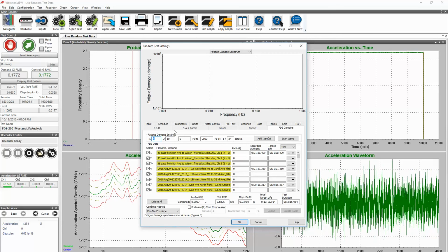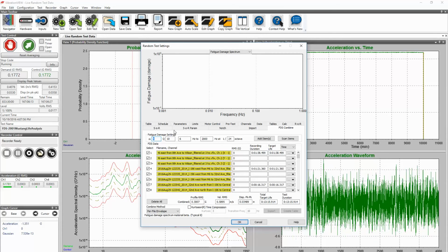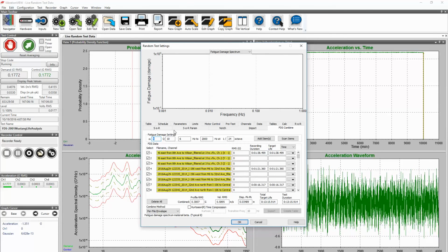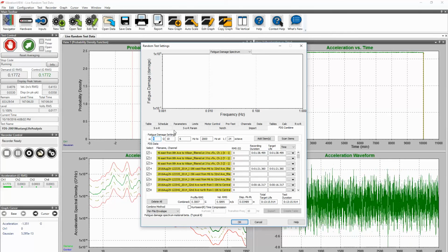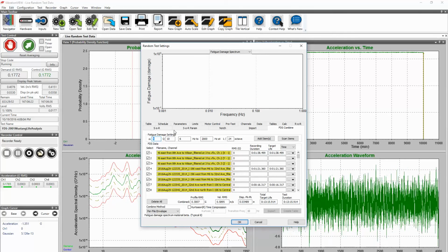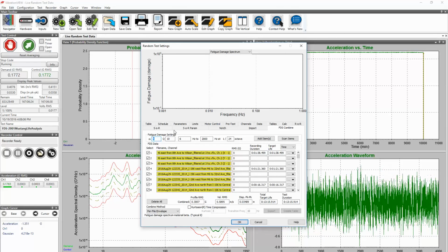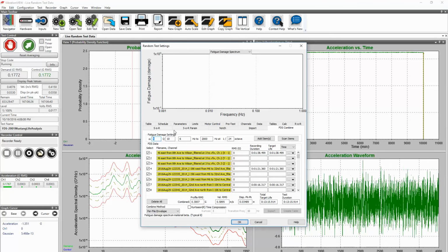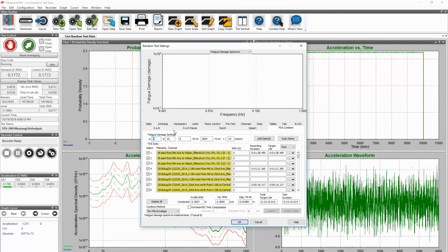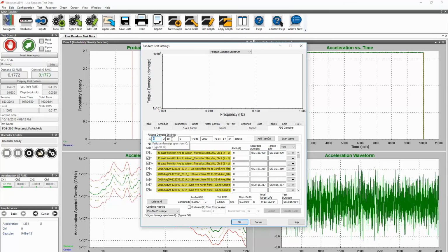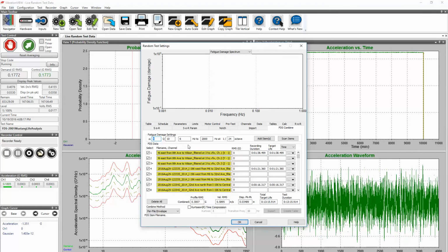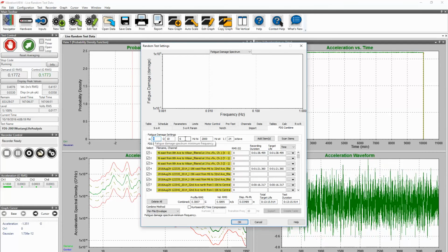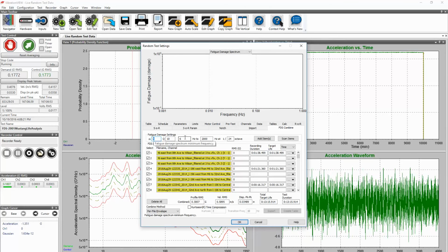And the Q, because we're assuming there might be a resonance in a particular situation, the exact Q doesn't make that much difference in the calculation. It'll smooth it out. It will make more resonances appear more pronounced if the Q is higher versus if it's lower. But a Q of 10, or whatever your favorite number is, 10 seems to work well.